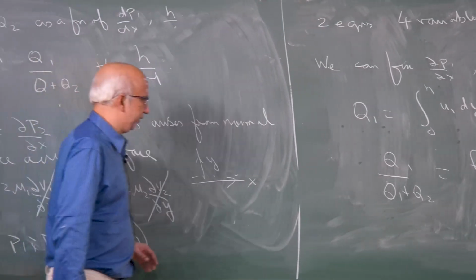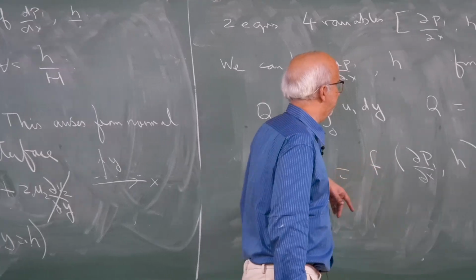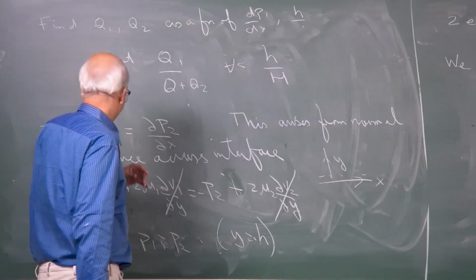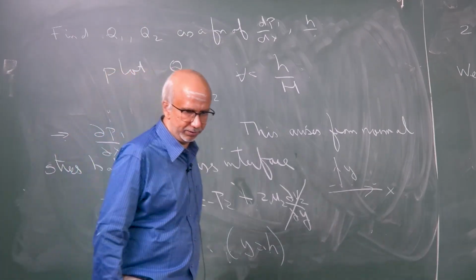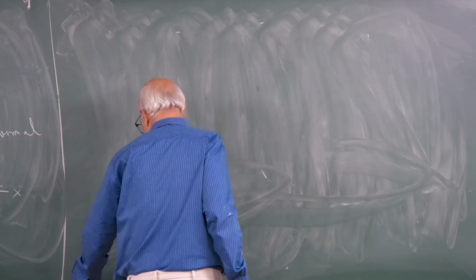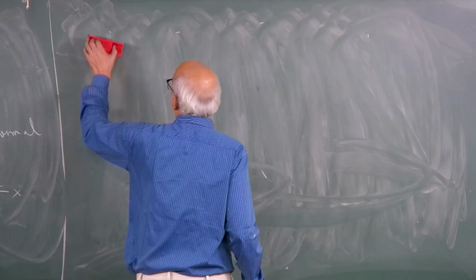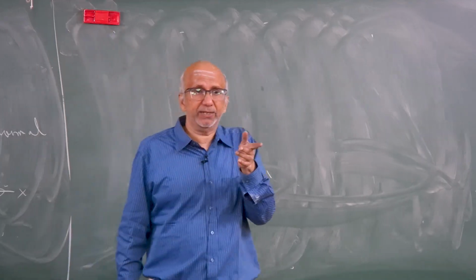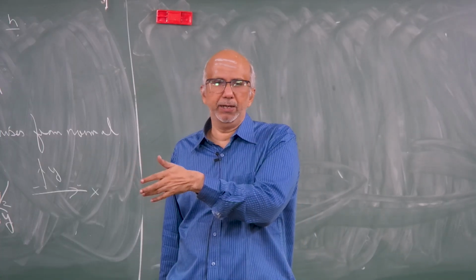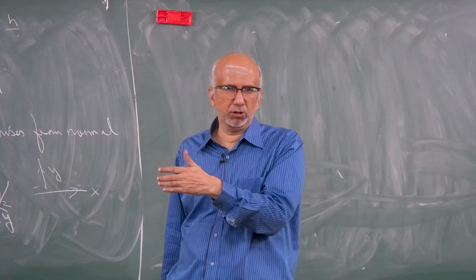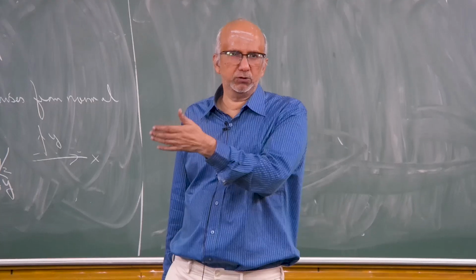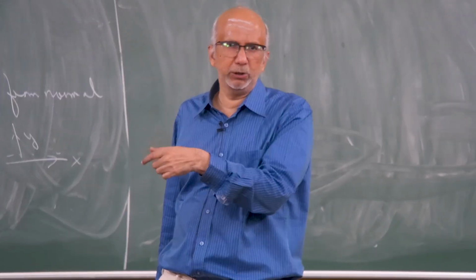This is something you are going to see in the course: how the shear stress is defined, how the normal stress is defined. So, what is it that has allowed us to come up with this analytical solution? The fact that the terms on the left hand side are 0, because those terms were the ones contributing to the non-linearity of the system. The equations were non-linear because of the inertial terms u1 du1 by dx, v1 du1 by dy.